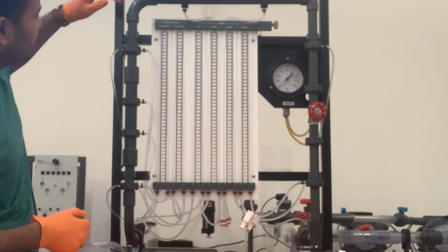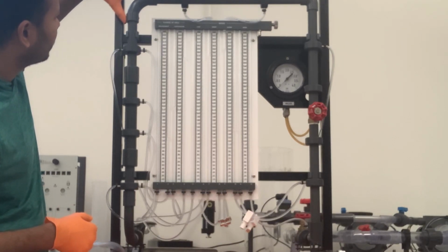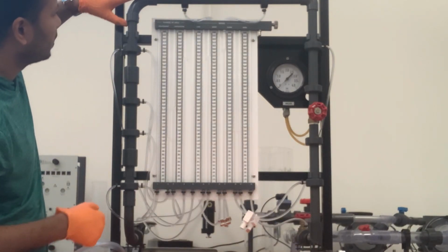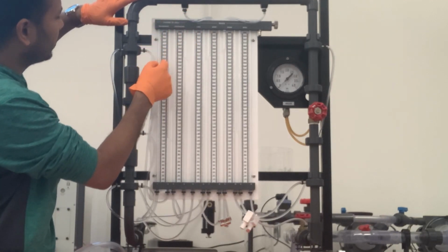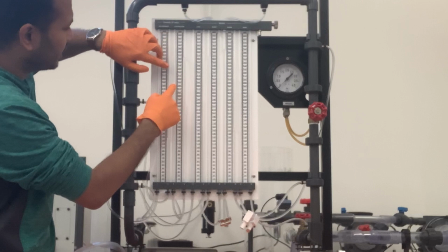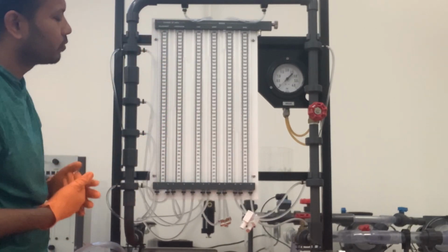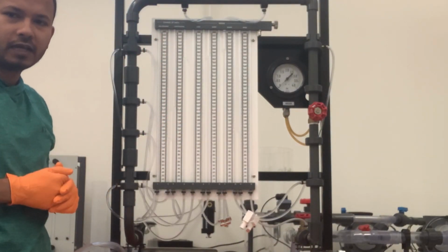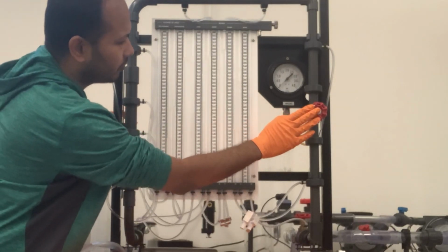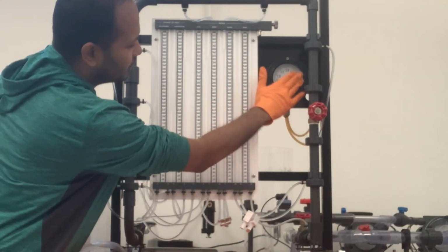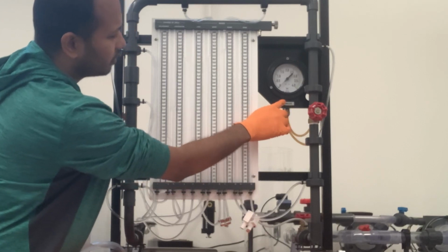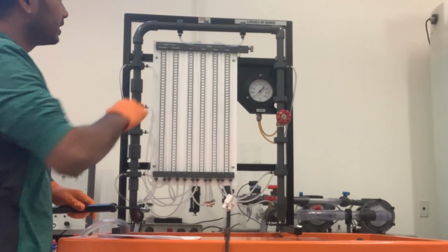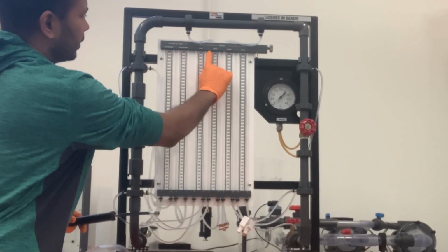Same for example, this elbow, this small bend, we will have one outlet after the elbow and one before, and if we differentiate between the two pipes, two manometers, we can measure the head loss. For the gate valve itself, we have the gauge here, or we're going to use this gauge reading. So this is the top part of the manometer here.